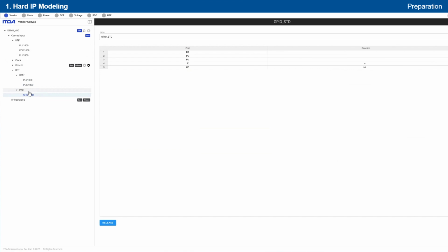And this is path control information used for the GPIO controller. GPIO normally has these kinds of control signals: pull up, pull down, drive strengths, input enable, output enable, etc. Also, you can add or remove as you want. This can be selected in the DFT MUX diagram.